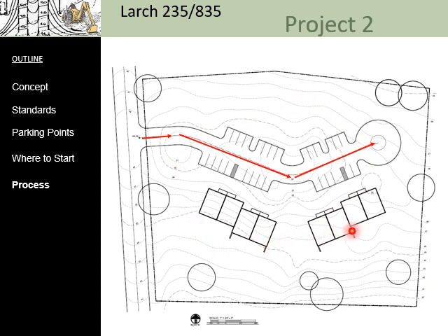All of these things are options that you want to play with, and you want to play with these in very rough numbers. That is, you want to work in 1 foot increments if at all possible. Yes, you've got a half a foot for the curb here, so that's fine, but you do not want to calculate in detail. You want to work in very rough numbers. Center line to the edge of the parking lot. Hop on top of the curb, distance there to the house, round it out. Come back here, jump down 9 feet, see if it works. If it doesn't work, go back and make a change.